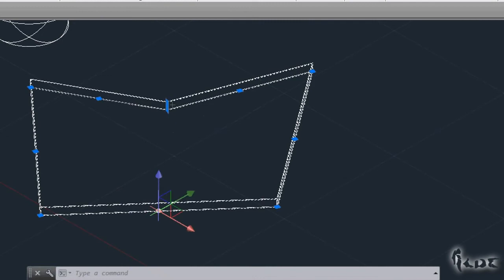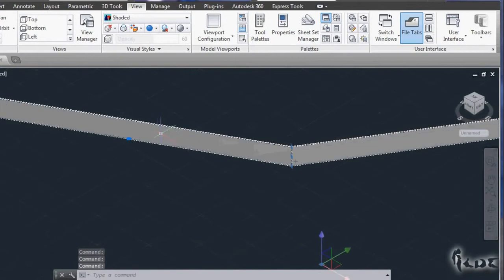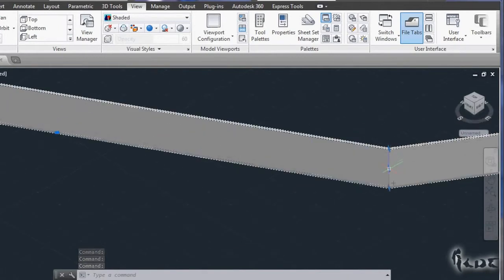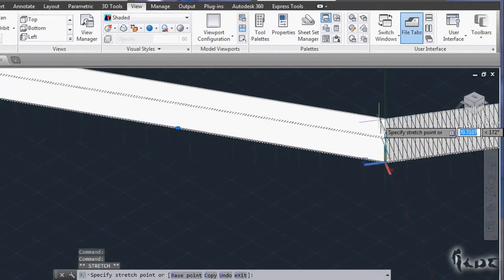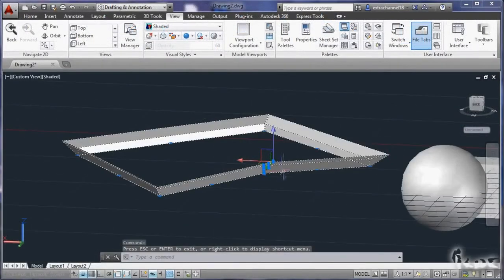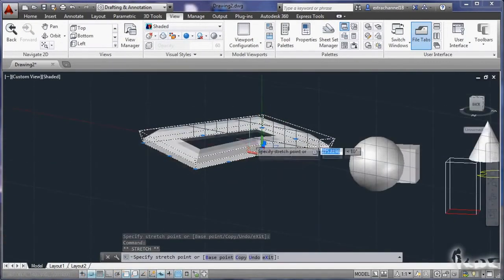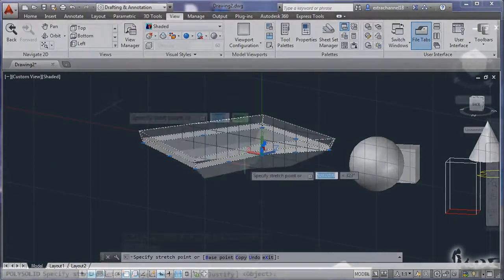Polysolids can be edited like normal 3D objects, although you have some extra editing points right in the space where you closed the polysolid first. These are used to change completely the polysolid in shape, extrusion and thickness in any direction. Enlarge the extrusion to manage these points better. Then start editing your polysolid completely.